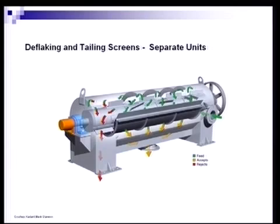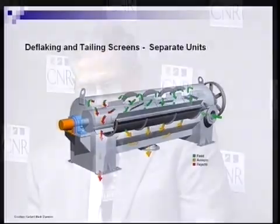And we add some dilution water typically in the body of the screen, which then washes the plastic debris away from the fibers. The fibers are recovered through the screen plate and taken off here with the orange indicated arrow, and then the plastics report out towards the reject end and are removed from the screen on a continuous basis. So this is a totally enclosed screen that replaces a vibrating screen, does a much better job in terms of efficiency of removal, and of course it's a much easier screen to keep clean and to maintain housekeeping standards in a paper mill.